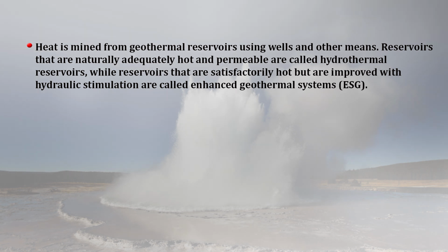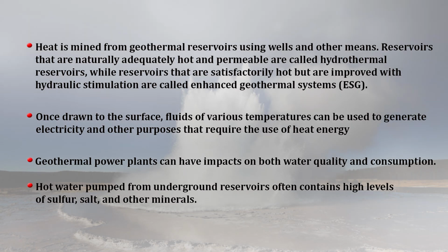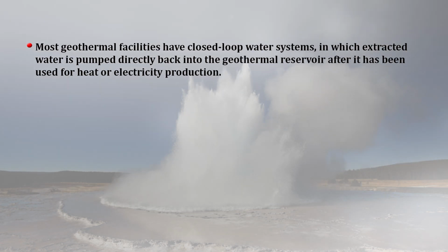Reservoirs that are naturally adequately hot and permeable are called hydrothermal reservoirs, while reservoirs that are satisfactorily hot but are improved with hydraulic stimulation are called enhanced geothermal systems. Geothermal power plants can have impacts on both water quality and consumption. Hot water pumped from underground reservoirs often contains high levels of sulfur, salt and other minerals. Most geothermal facilities have closed loop water systems in which extracted water is pumped directly back into the geothermal reservoir after it has been used for heat or electricity production.